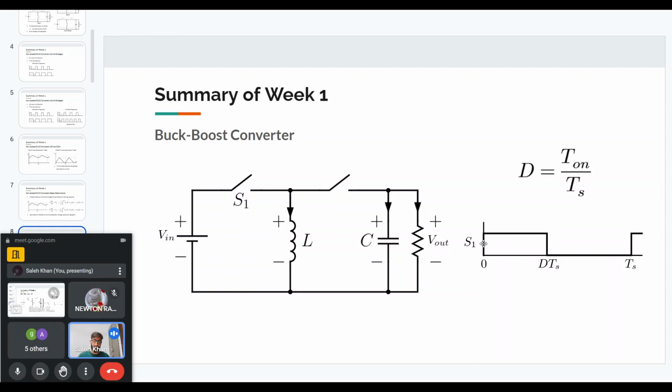If we have a higher switching frequency, then the ripple can be filtered out easily using smaller filters. That is why we try to have as high a switching frequency as possible. But the problem with high switching frequency is that the switching losses increase. Is that what you were asking, or are you asking something else? Okay, so in a DC-DC converter, the switching frequency is basically how fast the devices are turning on and off.